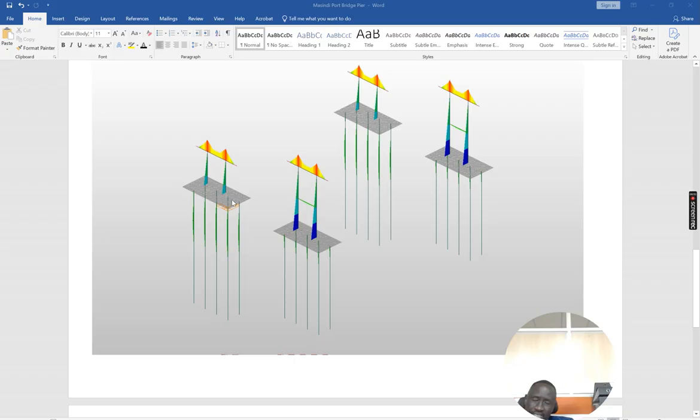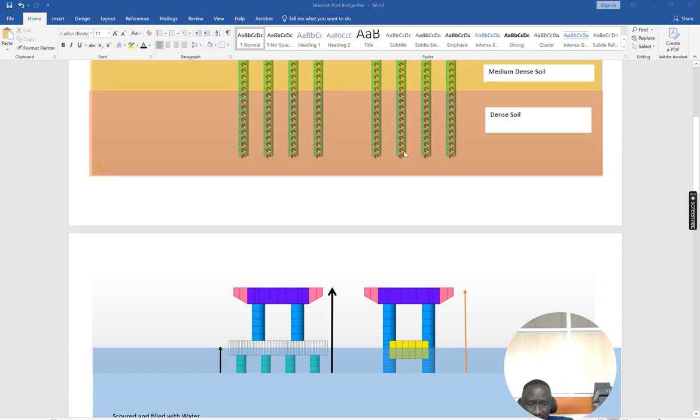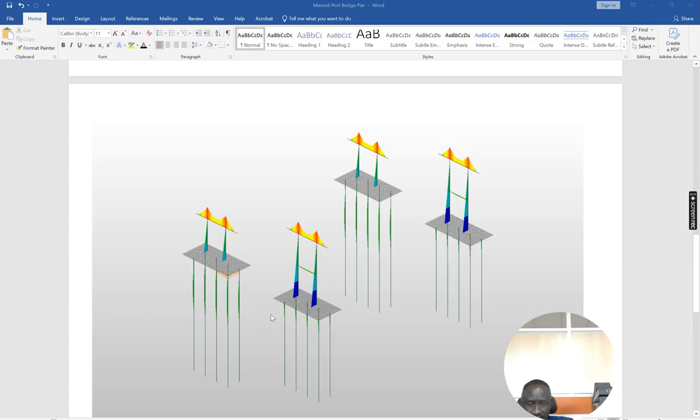So you find actually that the piles with the pile cap floating tend to have implication on the middle third of pile length downward, while the case where pile cap is at the riverbed, it appears that moment of this long, very high pier columns tend to be very, very high on the base than here.